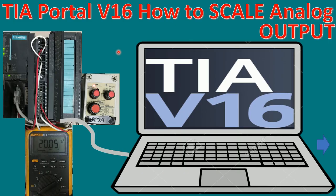Today I would like to show and share how to scale the analog output of PLC S7-300 by using TIA Portal version 16. In this case I will use a current loop source 4 to 20 mA and a multimeter that can measure the milliamps from the analog output.